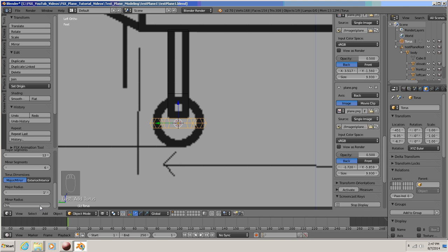So we're going to type in 4, and we're going to hold down the Shift, and on your keyboard, the button just left to your Enter key, hit that. And that is the symbol for inches and the Enter key. Now with your mouse cursor in the 3D workspace, we're going to hit R for rotate, and we're going to rotate on the Y-axis, so hit the Y key, and we're going to type in on the numeric pad 90, and then enter.